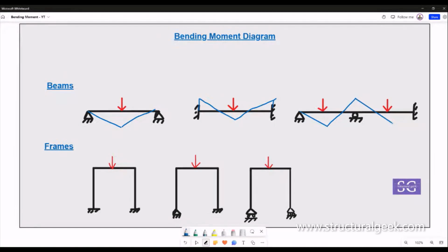In the second span, there'll be a positive moment at the base, and also there'll be a moment at the support. The important thing to notice here is that although the support is a roller, we still have a moment at this place. So the crucial part is how do we get that sort of moment? We get that moment by virtue of continuity. The moment coming from this beam is being balanced by the beam on this side. Essentially the support is not taking any moment.